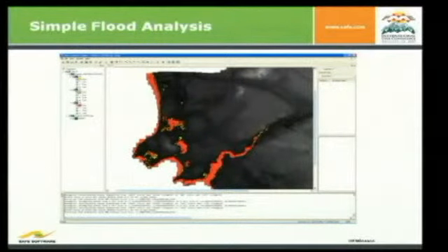But it's very powerful if you understand it, which I don't yet, but I managed to get an example from FMEpedia to work, and using the raster cell queries, we could get some rough model of how it would look if we raise the water level half a meter, 1 meter, and 2 meters. This is how it looks in the FME viewer now.